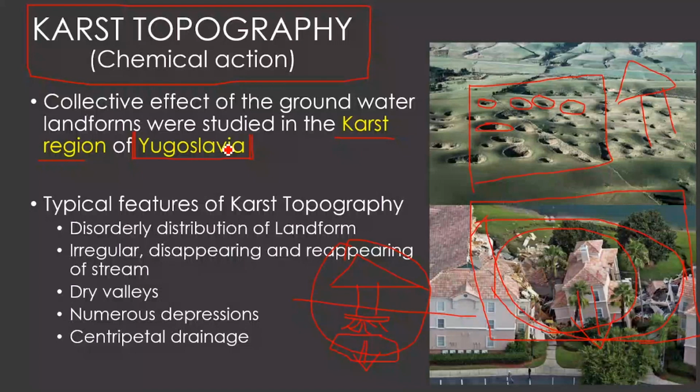Rather, if you have granite in one part, granite may not be that easy to erode, so it has very little chance of producing large cavities below the surface. But in an area where the subsurface has a rock type called limestone, a calcium carbonate rock, that will be easy to erode. We need to identify all these things when we are going for construction.